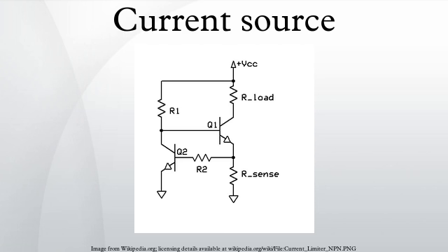Current sources with negative feedback. They are implemented as a voltage follower with series negative feedback driven by a constant input voltage source. The voltage follower is loaded by a constant resistor acting as a simple current-to-voltage converter connected in the feedback loop. The external load of this current source is connected somewhere in the path of the current supplying the current-sensing resistor but out of the feedback loop.